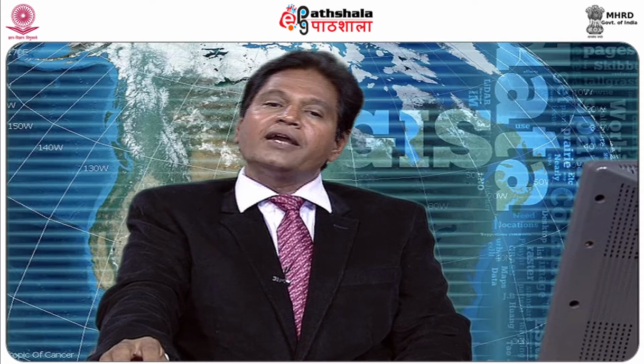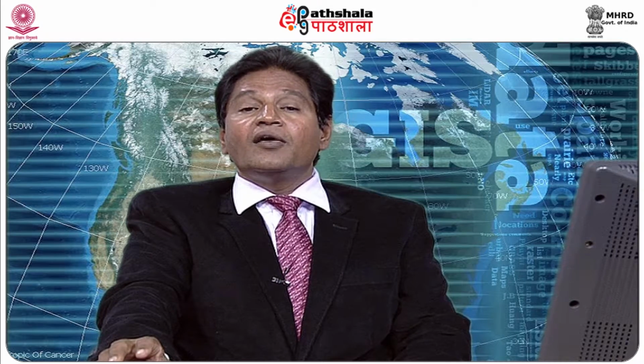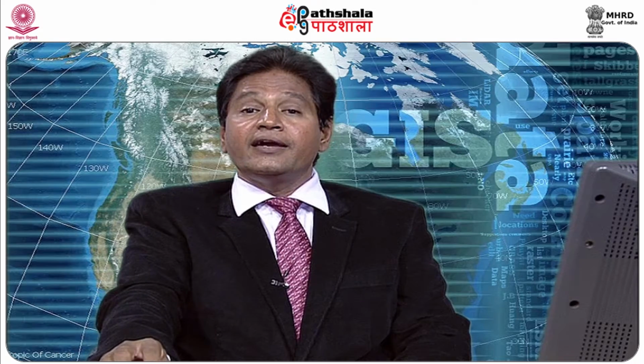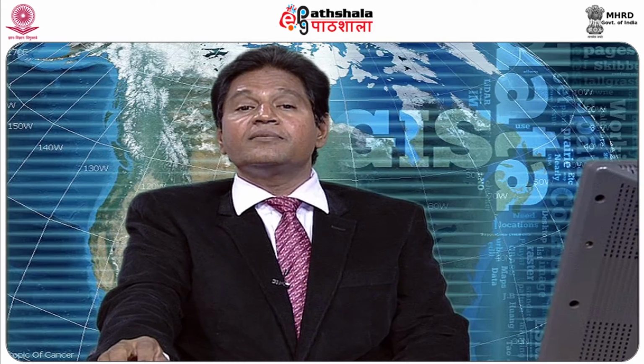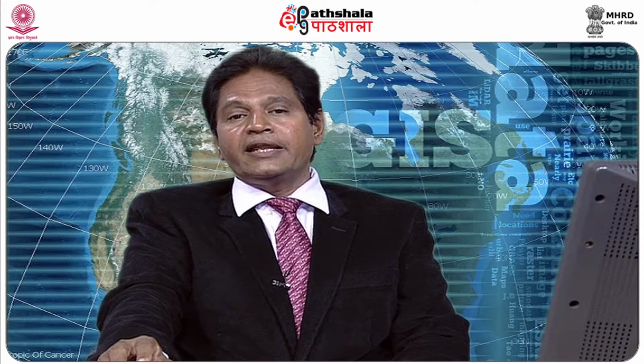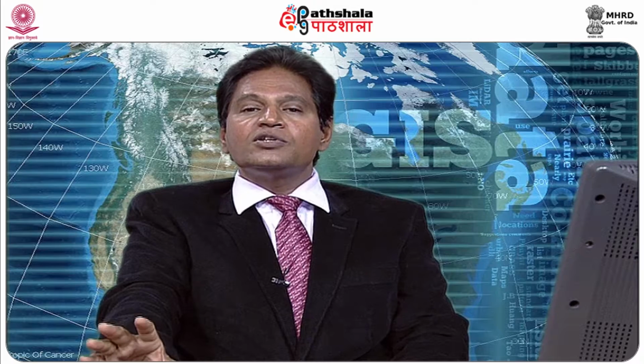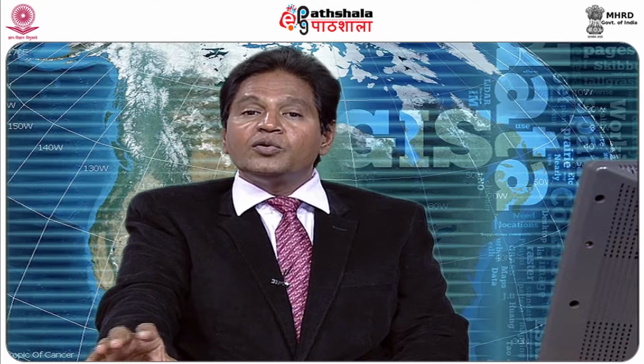Existing data, if I can bring it into GIS, and if I know the various terrain conditions, I can plan using GIS what I should do for the surrounding area: where all I am supposed to give, where it is not provided, where I can go for a sewerage system, where I can go for stormwater drainage. I was just telling you about the flooding. If you have flooding in a given area, to what extent will I be in a position to give a remedy to that area? In such a case, GIS plays an important role to identify zones of flooding and also give a remedy, how to go for stormwater drainage development and design.